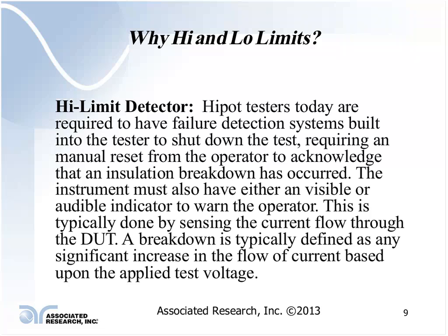as a result of that, we came back with an idea that, hey, if we're monitoring not only the high limits, but we set a low limit feature based upon how much current the product would normally draw, if the lead's open, we would know that right away and shut down the test, and that would eliminate the shock hazard from occurring again. So we built it into our products. We also built in the continuity test function into our products, so that it would be doing that test simultaneously.